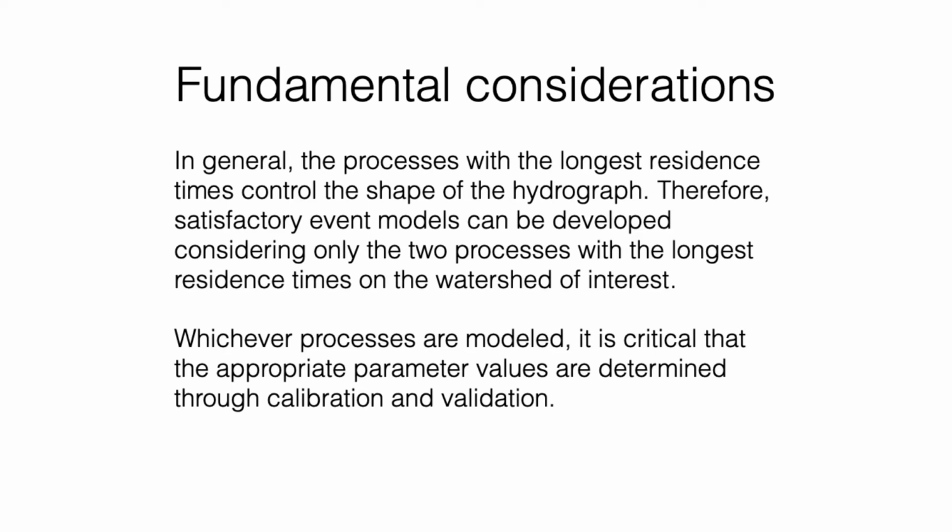It is very important to use different data for the calibration and the validation processes. The calibration process serves to make the model produce outputs that follow the real behavior of the watershed. The validation process serves to measure the quality of the predictions made by the model.